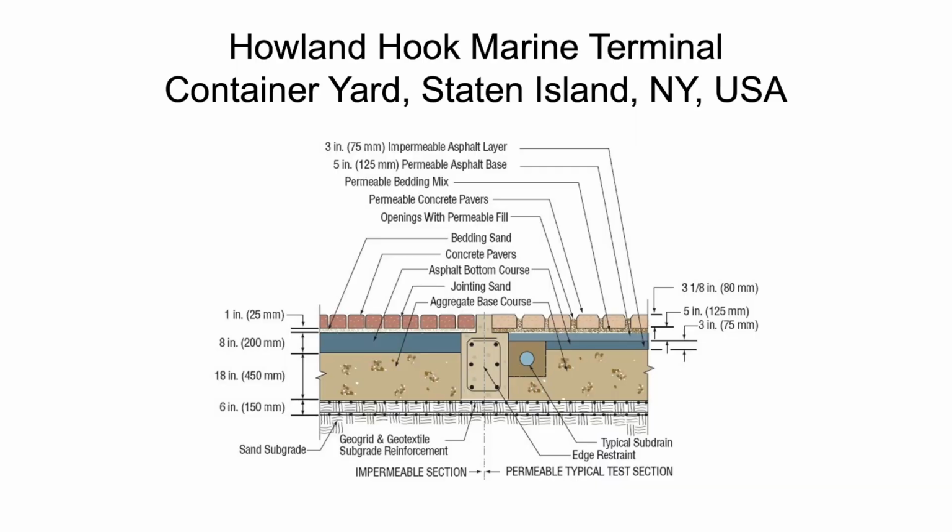And if you use a proper design tool like Design Pave, it will make sure you don't under-design. I have too shallow. So this is a very heavy application. It had a very large, very deep base course. But that's all you need to do. There's a cross-section of some of the, it varies across the thing because only certain areas you have the cranes and certain areas you have the containers. Other areas might have just residential, well not residential, but commercial and industrial parking. So it varies across the design.